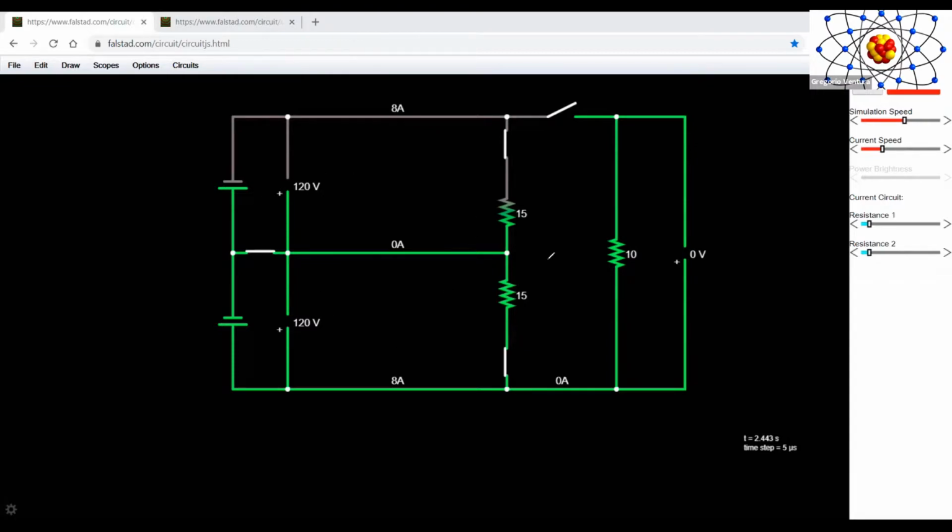Now that we have established the idea that it's important to have 240 volts for heavy loads, like residential dryers, the range, ovens, an electric furnace, a hot water tank if they are electric, all these heavy loads that require a lot of watts output and produce a lot of heat are better off using 240 volts than 120. And I already told you why: smaller overcurrent devices and smaller wires because of that.